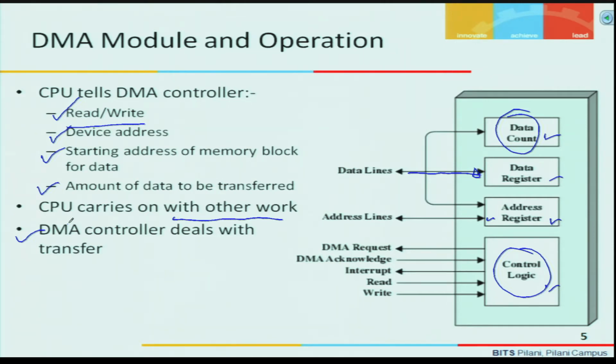So the bus is a shared medium. At that moment when the DMA is using the buses for the IO transfer, the processor doesn't have access to them. So the processor cannot access any bus at that moment. Then what other work can the processor do? The work which can be finished without accessing the bus or without accessing the memory. At that moment the processor can't access the memory.